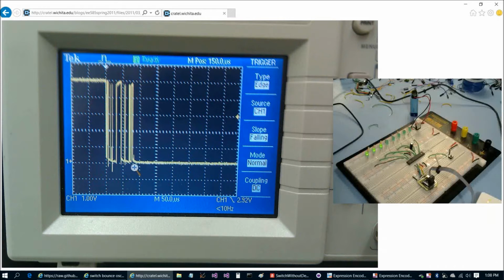So the other way to go about it is, each time the switch goes low, you can look for a certain number of consecutive presses, or you can look for an average number of consecutive presses. Like as of here, for example, you could check every so often, say from here to here, you could check the switch maybe 10 times, and you could say if 8 of the last 10 times you checked it, it was pressed, then we'll consider it pressed, something to that effect. But the point is that no matter what the software algorithm is, and there are plenty of switch debouncing algorithms out there, a lot of them pretty elaborate, so it can be kind of confusing looking at them sometimes, try to always come back to the thought that the whole purpose of a software switch debouncing algorithm is you're just doing in software what you're doing with your eyes when you look at this scope trace.